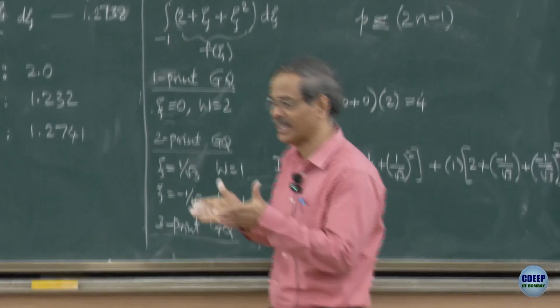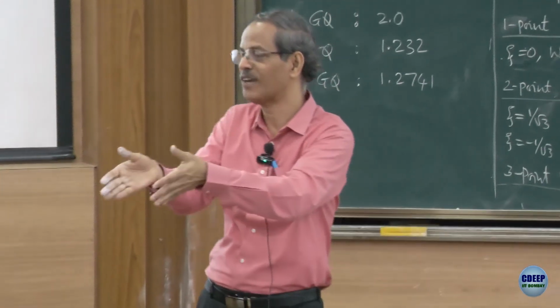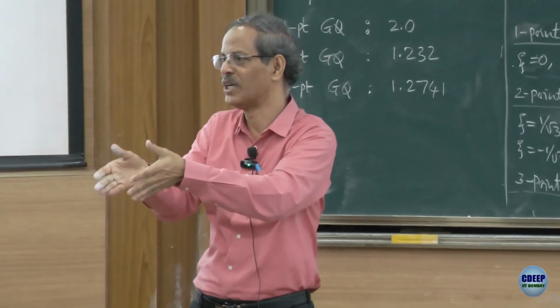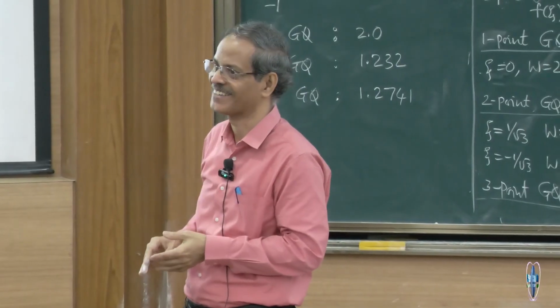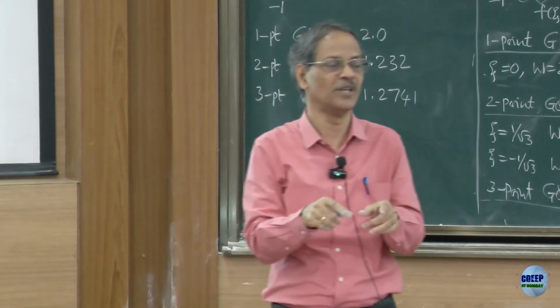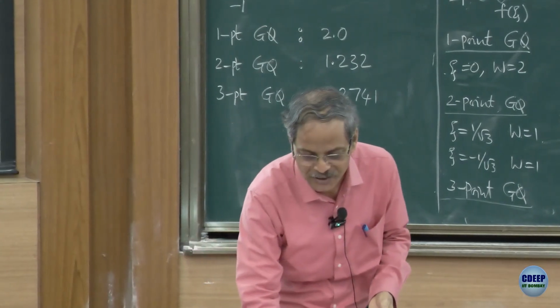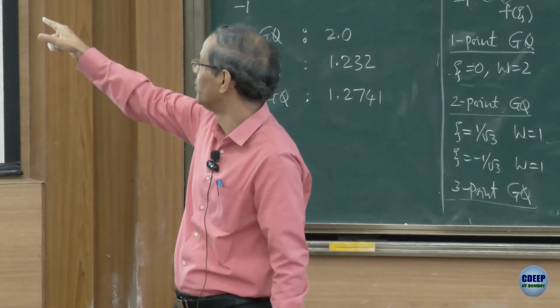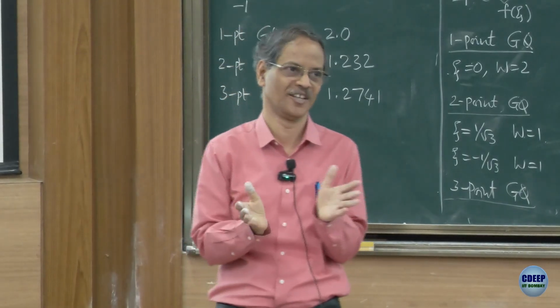So, if my element formulation tells me that it is likely to have higher degree polynomial terms in terms of eta, I will take more points there. So, you have to see which element you are formulating, what are the shape functions, what has gone into the Jacobian, B expressions and so on and so forth, then you take a call.